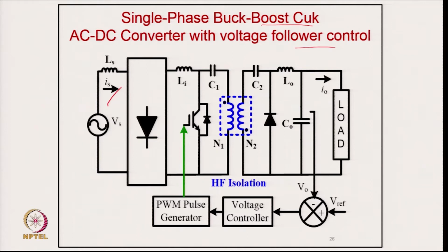But now you can understand here, we have 5 energy storage elements: the input inductor and output inductor. Because of the transformer in between, we divide the energy transfer capacitor in two parts, like C1 and C2, and then we have a magnetizing inductance of this transformer. So, now you have 5 elements, and 5 elements means you will be having 2 to the power 5 designs, that is virtually 32 designs of this converter. So, you have to select out of 32 designs which one is the best for you. Of course, we look into that.